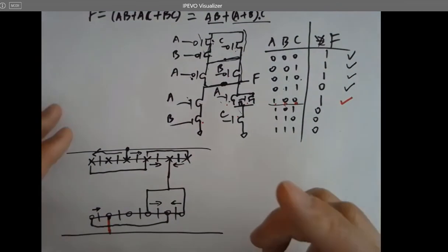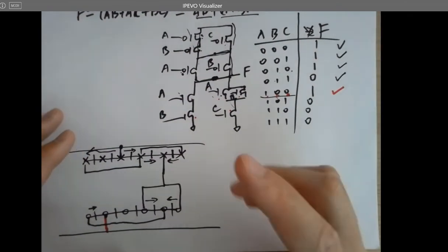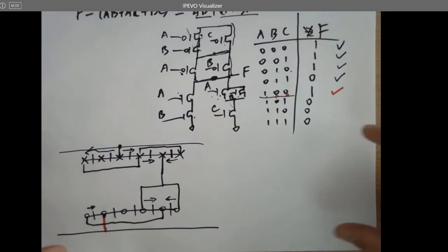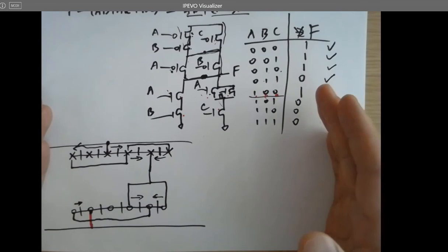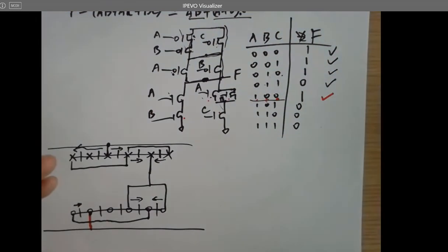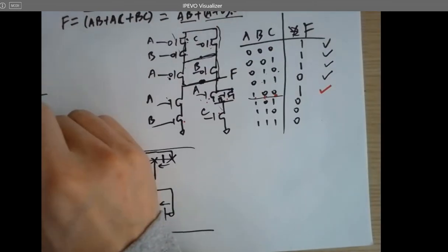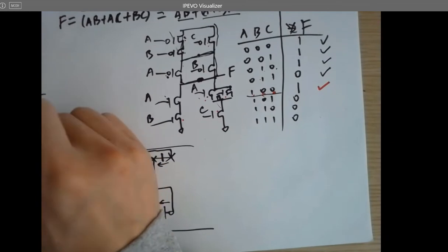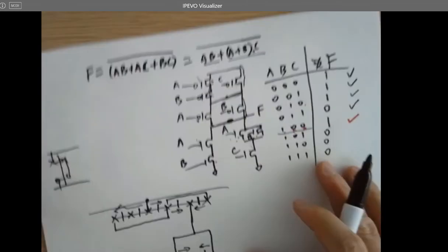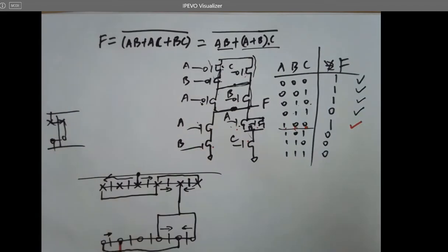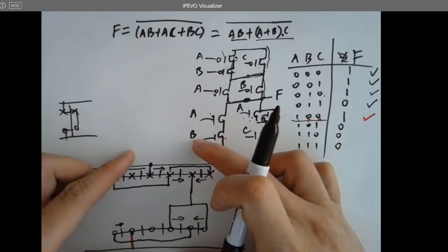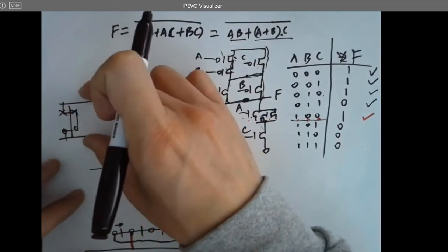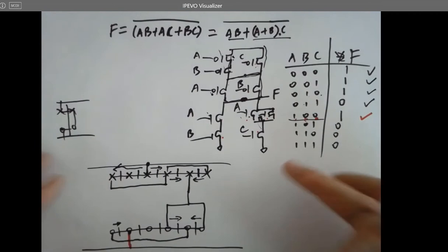But keep in mind, there's one tip here, because eventually you are going to build a functional block in Electric VLSI. So at the very beginning, I draw an inverter because an inverter is super simple. You don't need that much space in the middle. So I normally just draw a really tiny inverter like this, right? And after I have all these other structures designed, I have to expand it to make more space in the middle to run the traces. And I want to place this inverter, along with all these structures, to make one block.